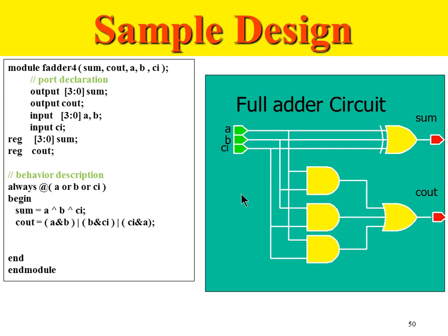The logic of always block 1 will work parallelly or concurrently with respect to the logic of always block 2, and that will work parallelly with respect to always block 3. That is how you can build concurrency in Verilog. If you want to execute parallel logic, put that logic in two separate always blocks. That will work parallel. But anything inside the always block is sequential, one after another, just like C language.